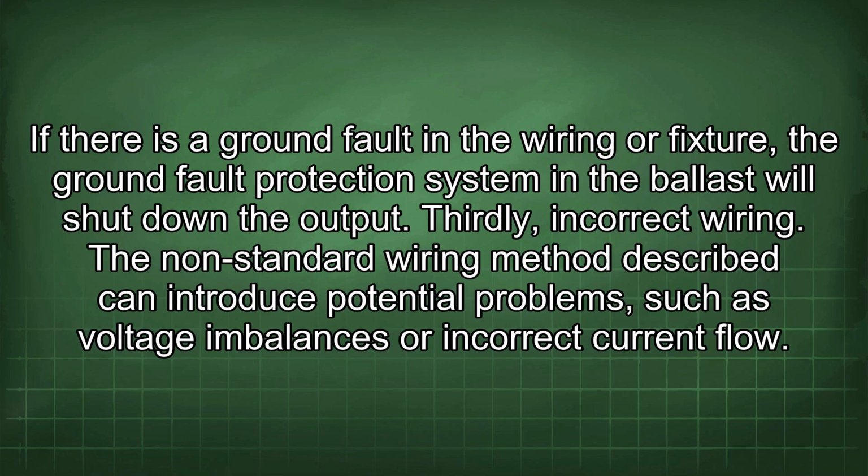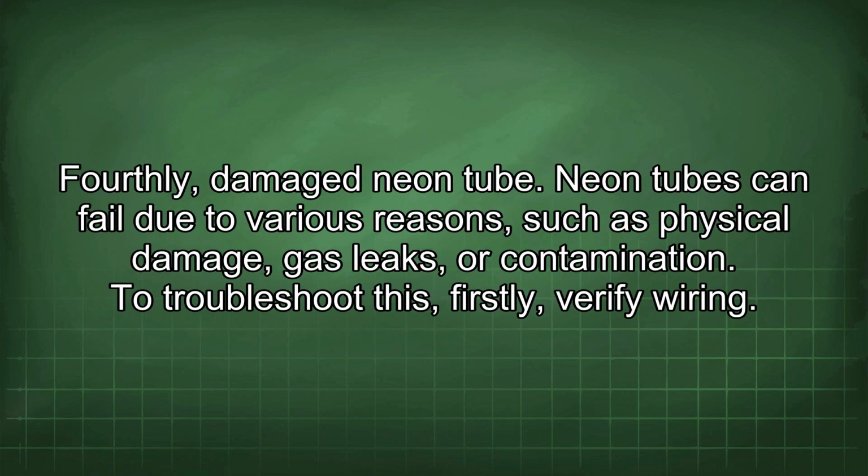Thirdly, incorrect wiring. The non-standard wiring method described can introduce potential problems, such as voltage imbalances or incorrect current flow. Fourthly, damaged neon tube. Neon tubes can fail due to various reasons, such as physical damage, gas leaks, or contamination.